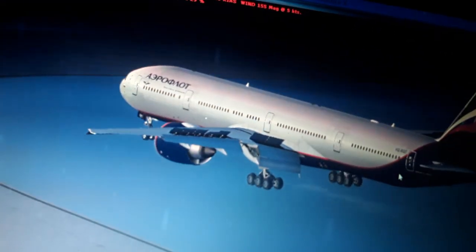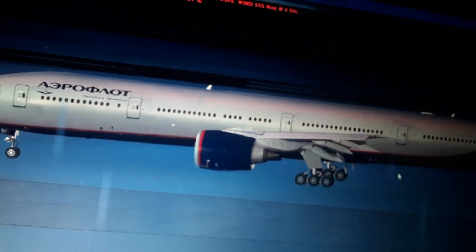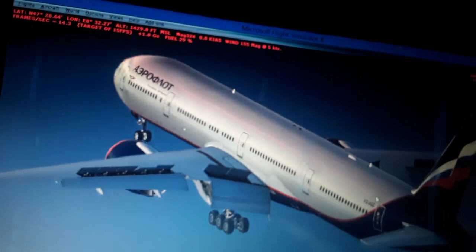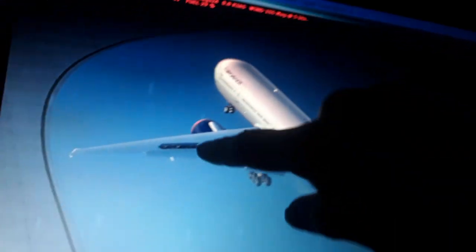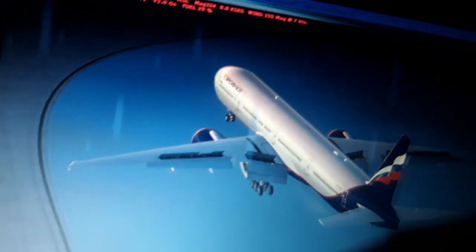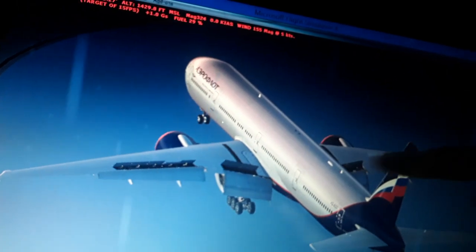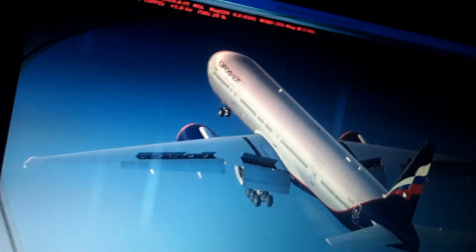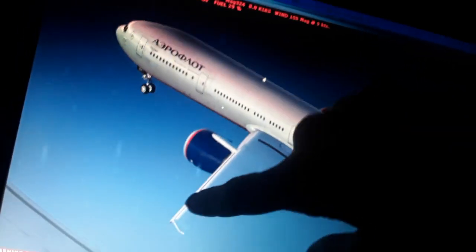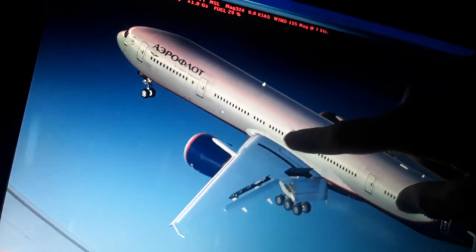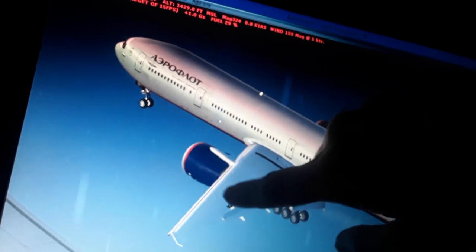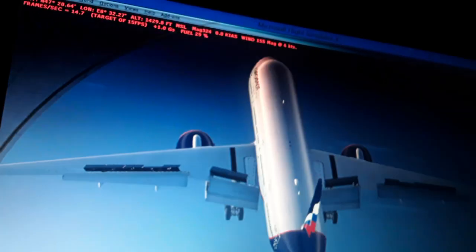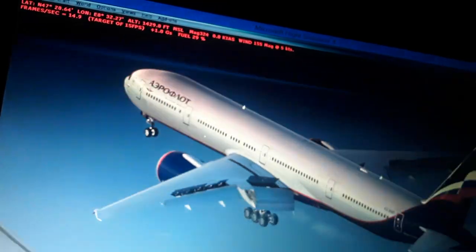Also, we have the airflow as the aircraft accelerates. We have the mean aerodynamic chord position, here at 25% of the wing chord, approximately from the forward leading edge. It's the position where the maximum aerodynamic lift is being produced, and also the position where, once the stall begins, the airflow begins to detach from the top of the wings.